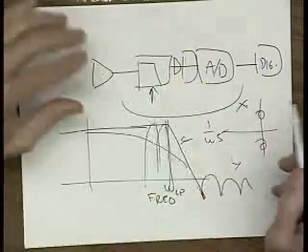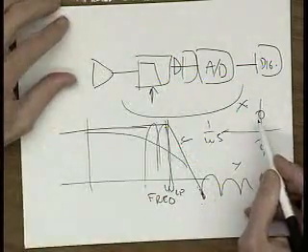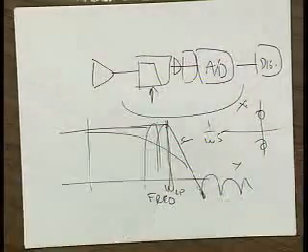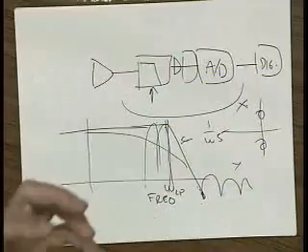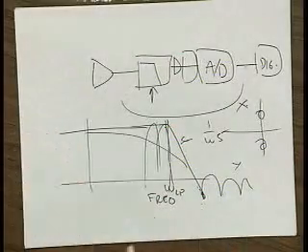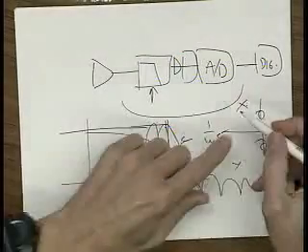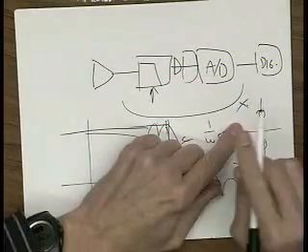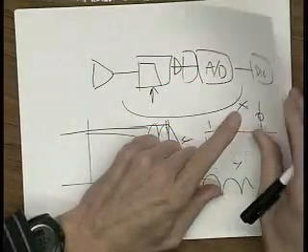Your problem right now in this op-amp thing is to kind of move these poles around a little bit. Our basic approach will be to take your op-amp that's stable, put feedback around it so that we can create poles and zeros at particular spots. And that turns out to be real easy to do. Okay? So how do you do it?